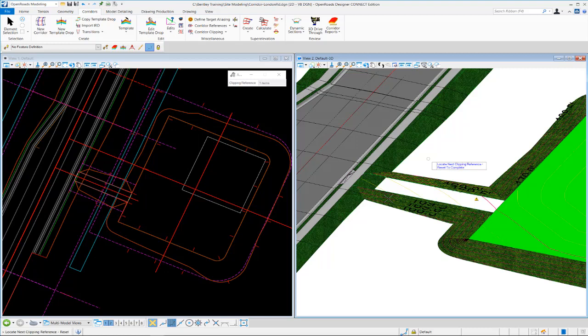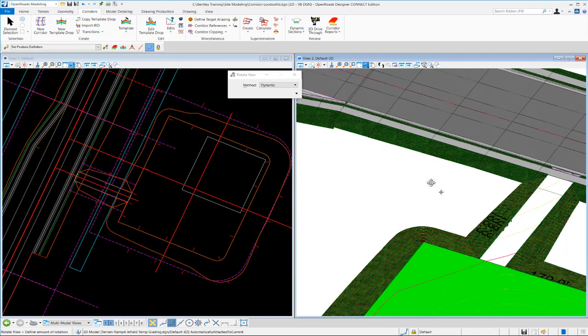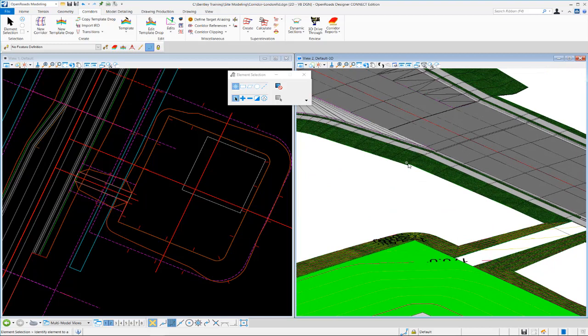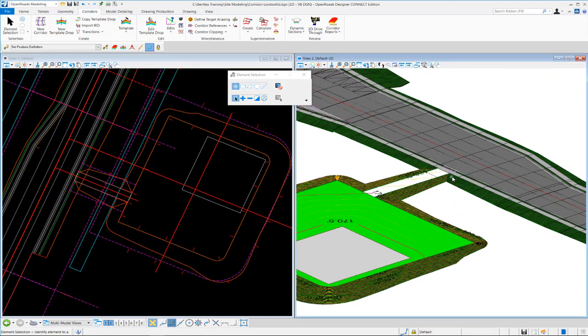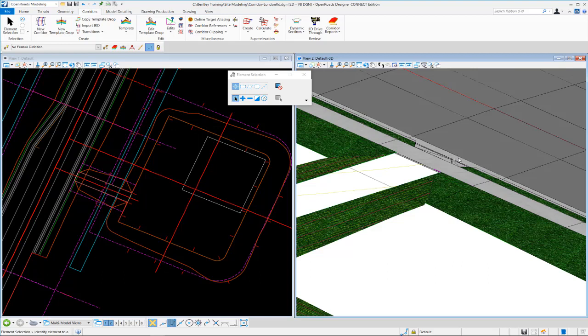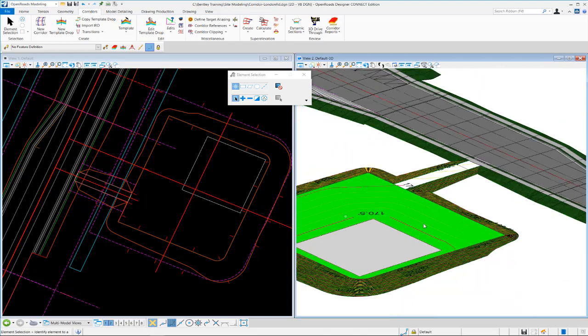It's going to go through and do some processing, and it's going to remove the areas of overlap there. So you can see it cleans that up quite nicely with the side road corridor or the mainline corridor for London Road. You can see how that connects up quite nicely, just like we want. We have our little drive apron there and our sidewalk, and then now we have our gravel drive with all of our grading along the outside edges.